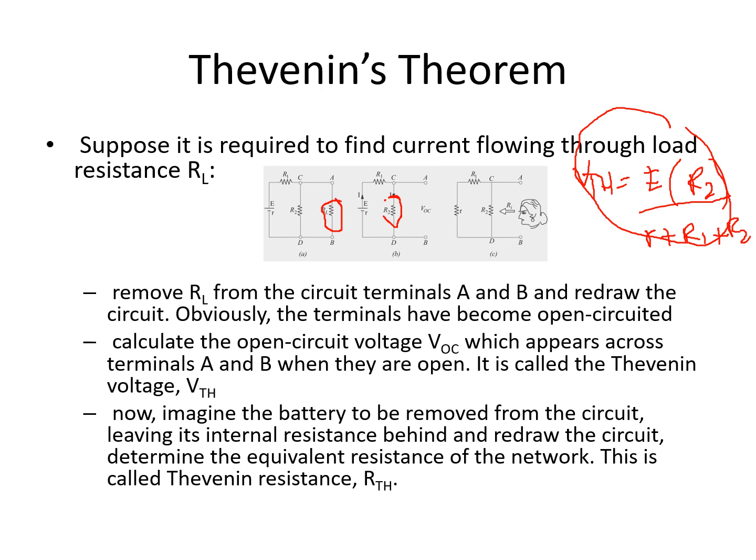Every time you are getting the value of an equivalent resistance or a total resistance, there should be no sources involved. So if we're going to remove the voltage source here, what will remain is your internal resistance R, your R1, and your R2.